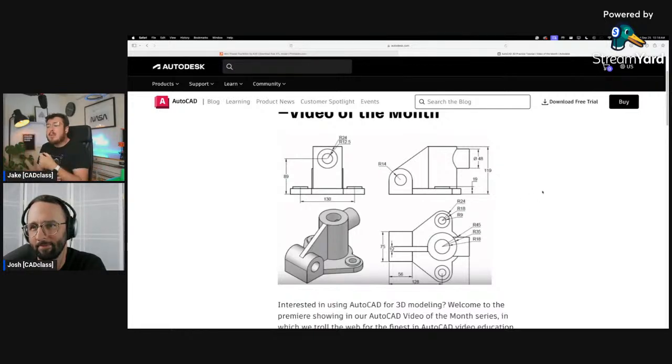As always, the first thing I want to do is get rid of all the features that I know I could make in a couple of operations. This horizontal tube that's coming out is obviously made and projected onto this ribbed surface. That's why you can see that it's interfering along that vertical tube. And the rib in the bottom left-hand corner, I can make very simply with a sketch and then an extrusion. But there's also a tool called Rib that's mainly used in plastic injection mold facilities. So if you've never touched it, don't blame yourself. I very rarely use it.